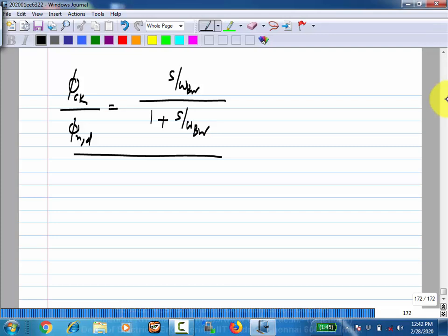Okay, so this again, if the delay line is jittering very rapidly, then you can't track it. But if jitter is slow, then the loop will compensate for it. Okay, slow changes in delay, you can compensate for it. That's all. Okay, and you can calculate the output contribution from this, right? So we will revisit this when we come to other kinds of CDR. But basically, this is what you do, right?